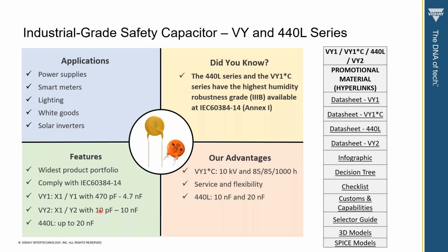Capacitance can be from 10 picofarad for the VY2 up to 20 nanofarad for the 44L series. And our advantage is our VY1 is tested under 10 kilovolt and 85/85 standard for 1,000 hours. And the service and the flexibility.